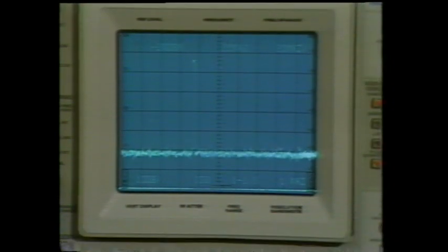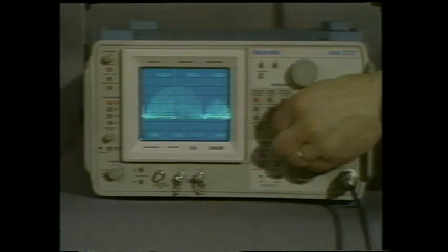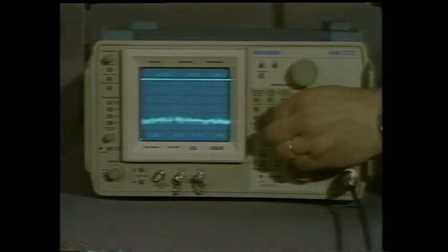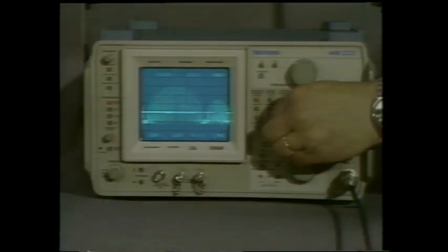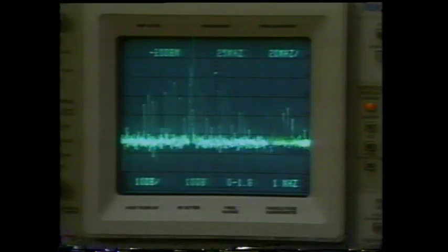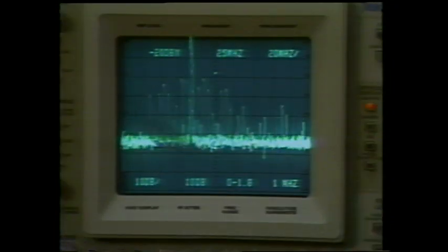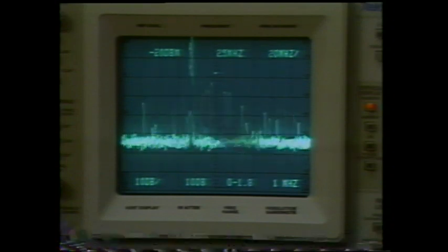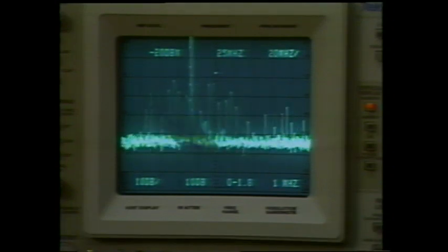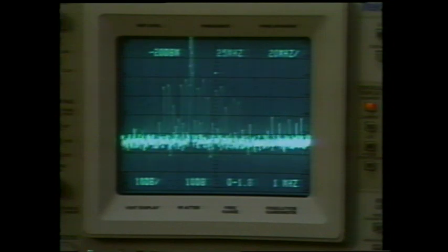Here's a spectrum of a narrow pulse signal. Notice that we lose almost all of it as we average this low repetition rate pulse train. If the signal is large, we can set the digital peak-to-average cursor between signal and noise, so the noise is averaged while the pulse signal is unaffected. This isn't possible for small signals. At lower rep rates and narrow pulses, digital storage can't quite catch the pulse peaks. As you can see, the shape and level of the spectrum differs with digital storage on and off.